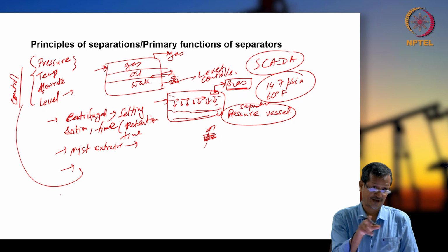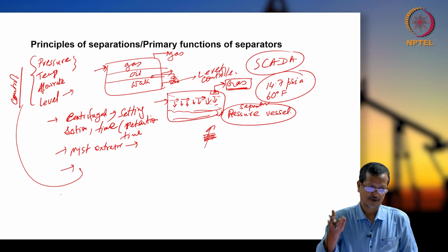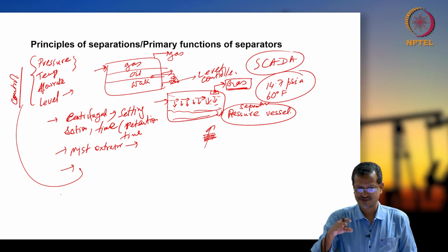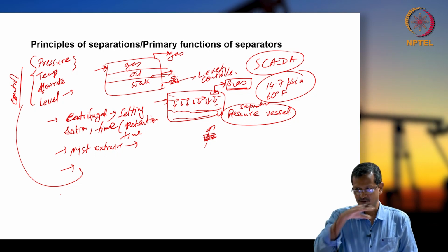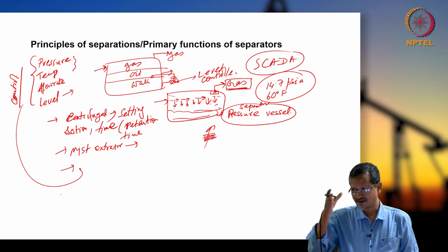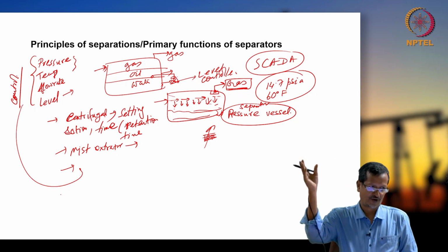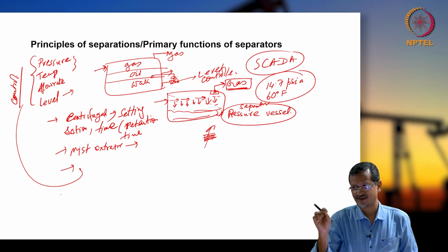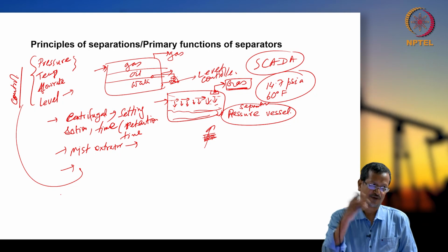That's why I already told you about the sand control mechanism. With sand control you reduce sand, and you also set your production rate in such a way that water coning does not occur, so that you are not getting only water instead of oil. Okay. So your production rate should be optimized and your sand control mechanism should be working. In that way you are reducing both and you are getting more oil and gas, but anyway you cannot make 0 water, 0 sand. You will get a certain amount, then you have to handle it on the surface.